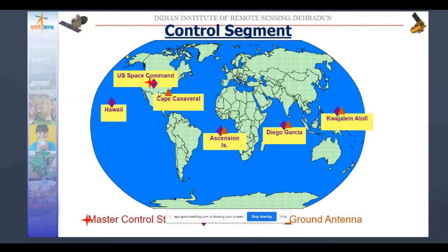That information is what we call the satellite position, x y z or x dot y dot z dot. These x y z, x dot y dot z dot are Cartesian coordinate information, which can also be converted into Keplerian elements. When we talk about Keplerian elements, we have the semi-major axis, eccentricity, inclination, right ascension of ascending node, argument of perigee, and the anomaly.